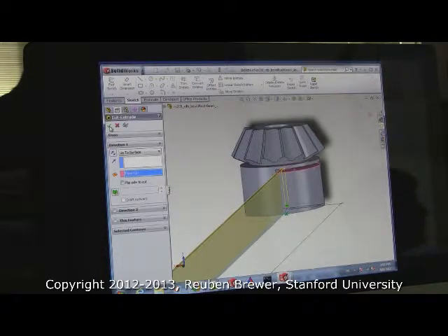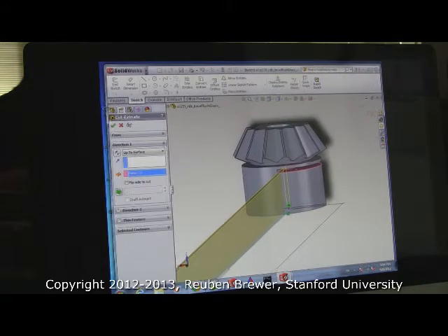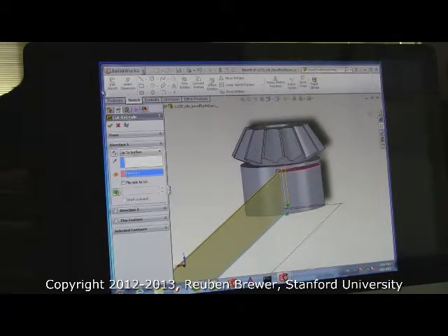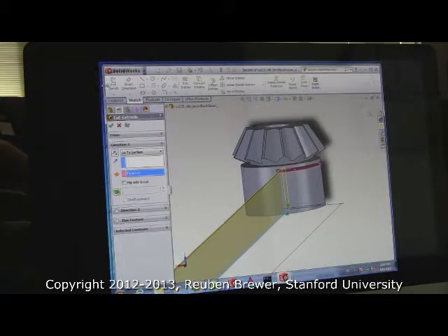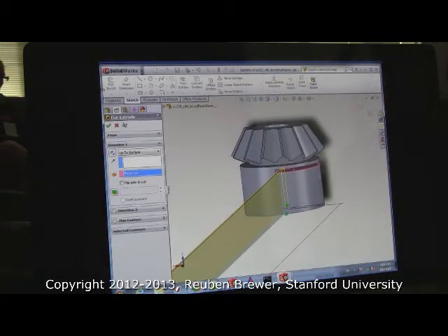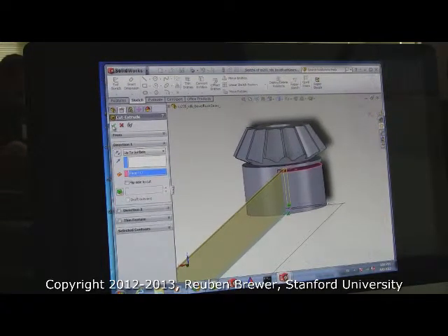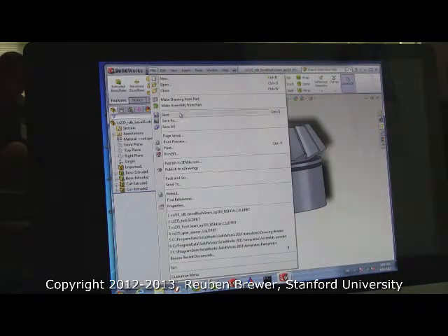Everybody got a cut? What kind of rectangle did you use there? A corner rectangle. So one corner in the center. Yep, one corner is good. Yep, exactly. Yep, up there. Good. And then smart dimension. Excellent use of zooming. Yep. 1 millimeter. Okay, has everybody got a cut? Awesome. Go ahead and save.